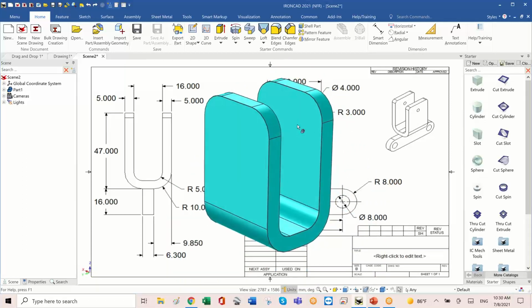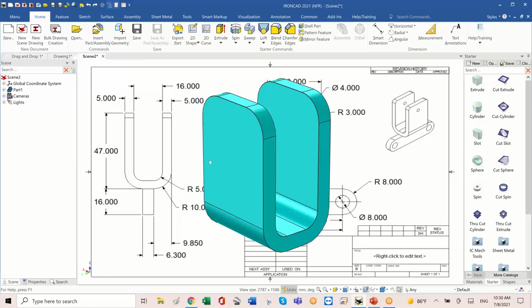So how are we going to do that? Because I know if I drag a part out here and touch this, it'll add it to it. Well, in IronCAD, anytime you're uncertain, use the right mouse button, because now watch this. Take this slot feature and drop it there, but I used the right mouse button, so it gives me a menu. And that's really cool. So what do I want to do? Do I want to drop it as an intelligent feature on this part, which is the default? No. I want this to be a part. Watch this. Okay, drop it as a part.